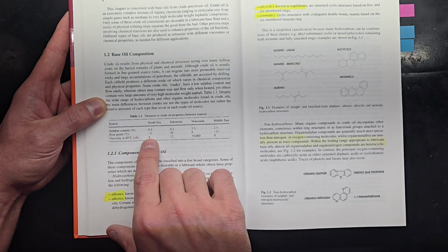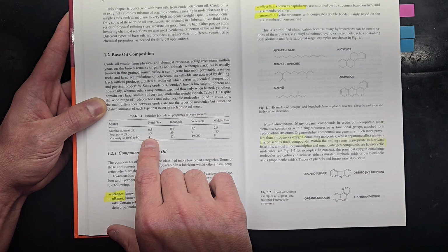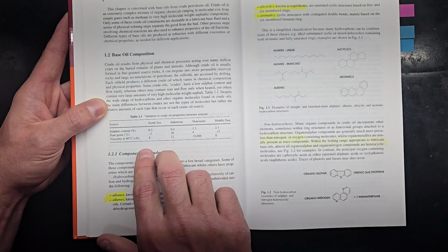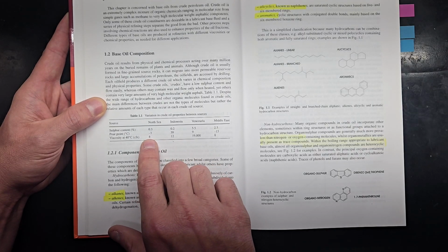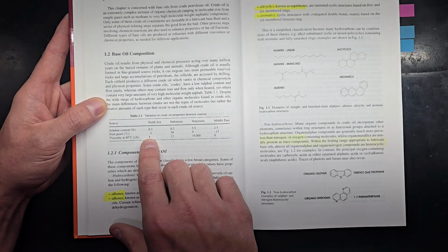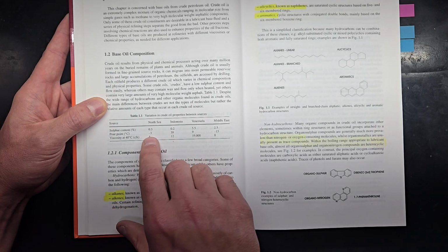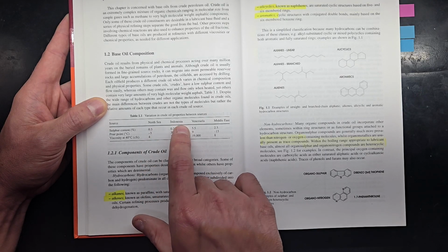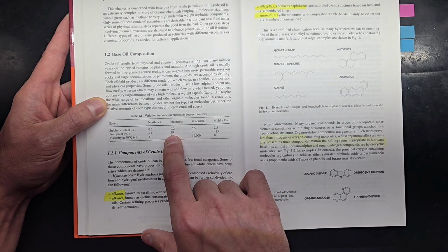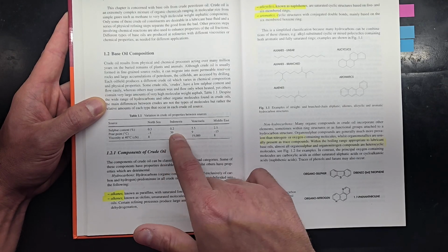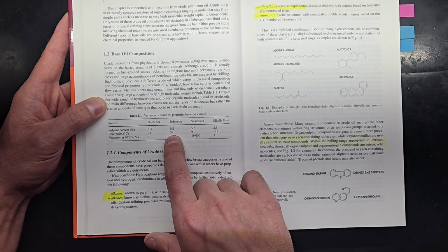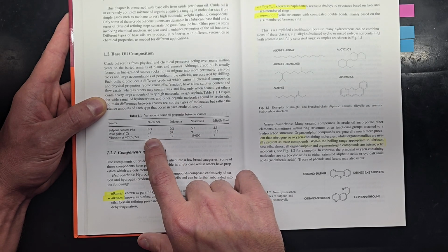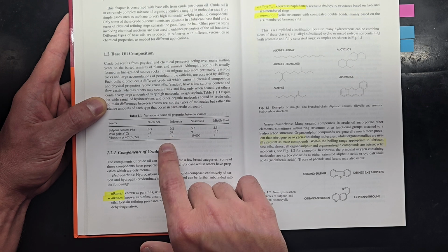The pour point, so the lowest temperature at which the oil is pourable. I know there's a little more refined definition for it than that. Crude oils that we get from the North Sea have a pour point of -3. Crude oils that we get from Indonesia, 39, 40 degrees Celsius. So those two are very, very different crude oils.